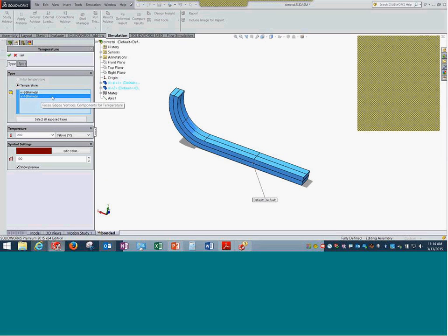Second, ensure you are selecting the bodies, not surfaces. That's what I want to highlight. Second, the temperature: you can apply the appropriate temperature. So this entire set is increased from 25 degrees Celsius to 280 degrees Celsius. That is the only thing happening.